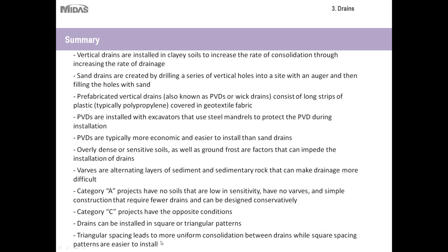Square spacing drains are very easy to install just because the geometry is very simple, whereas triangular spacing leads to more uniform consolidation. However, it takes a little bit longer. It's a little bit more complex to design for.